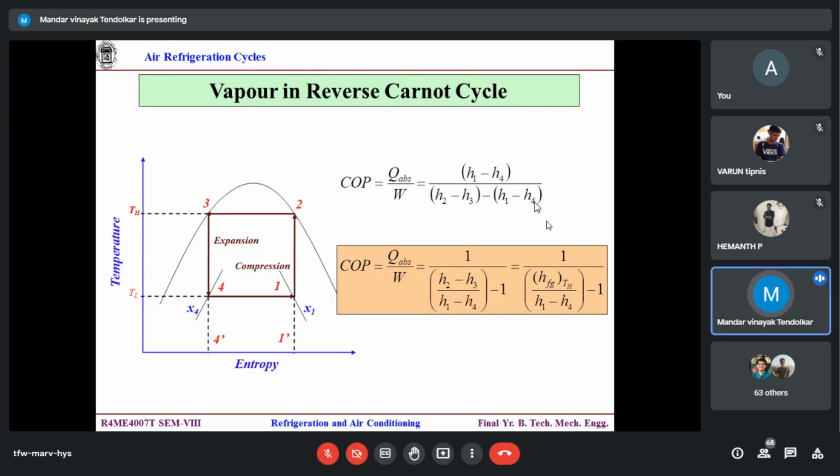How do I expect a reversible expansion, I have to say isentropic expansion, with a wet part? Always remember this thing: your expansion starts as a liquid. Liquid expansion is very difficult. It's an incompressible one. At the beginning, it is entirely liquid, 100% liquid. We are assuming that after the expansion, let's say it reaches over here, then maybe dryness fraction some 5% and 10%, whatever it is, and then finally let's say over here 40%. Then it is okay. But what at the start? There will be tremendous inertia for the expansion because it is liquid.